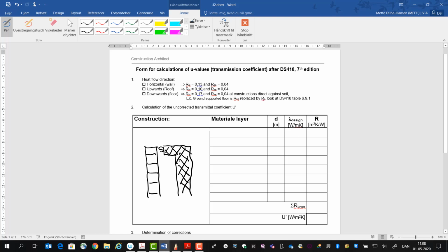And I have insulation here in the cold bridge, and we have the window here. So where we are looking is now here, U2. So again, first we meet is Rsi. So we cross up here and write Rsi, so 0.13.